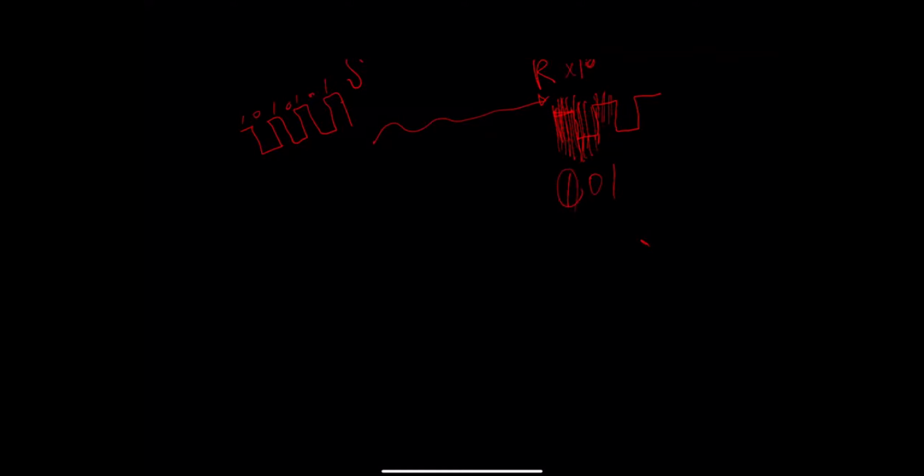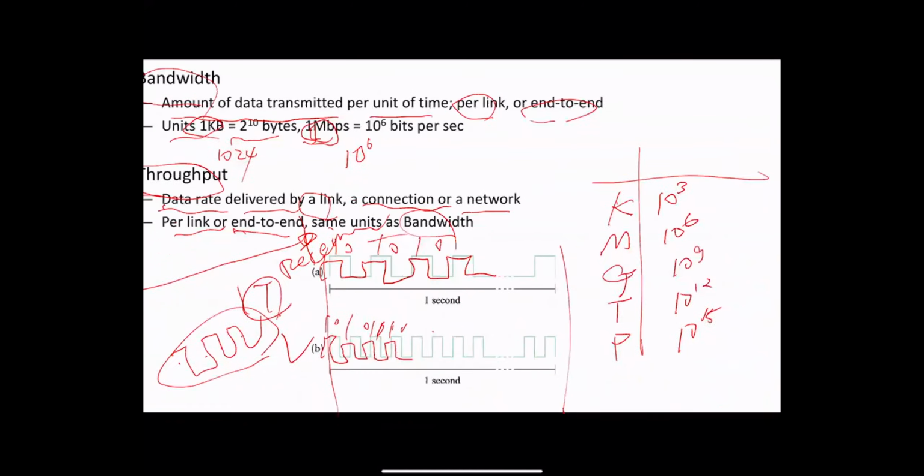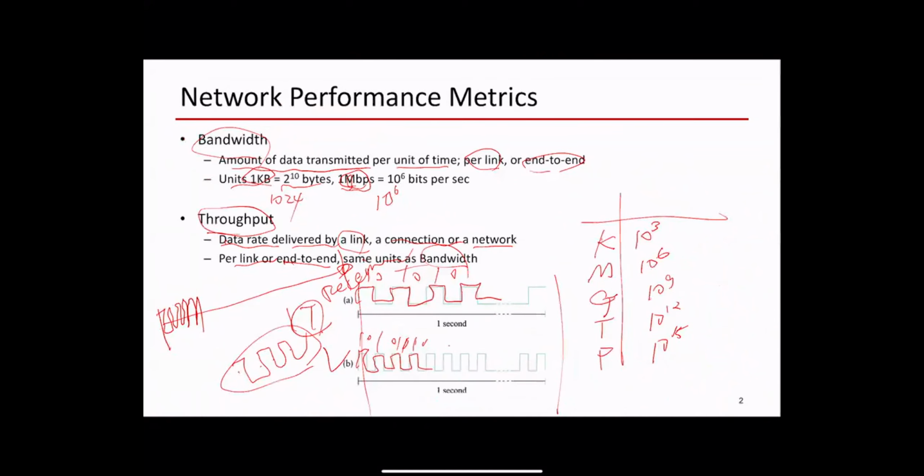So what's the issue? Let's say I sent the information at gigabit speed. If your sender is sending at gigabit, your receiver has to have the ability of 10G for oversampling.